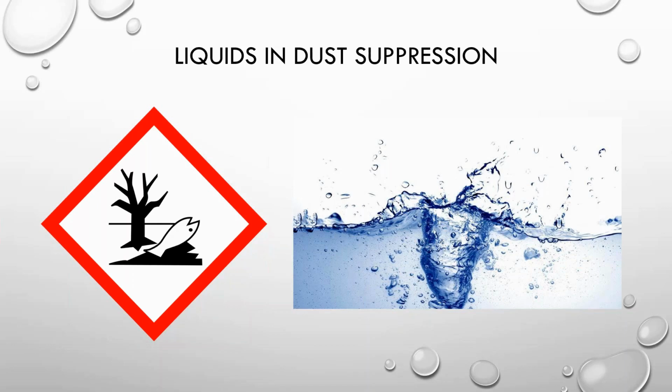This is where efficient methods of dust suppression need to be explored, which we will come on to later in this webinar. Other ways of sourcing water can also be from an on-site lagoon or even rainwater capturing vessels. Sites should be careful with salt water in dust suppression equipment, as this can perish seals in pumps and cause premature rust and wear in machinery.